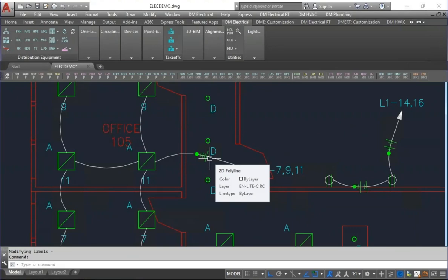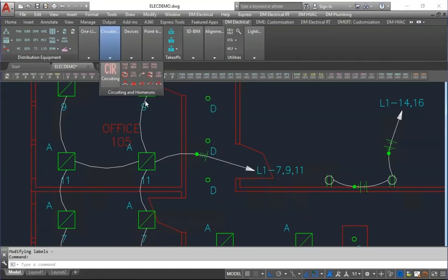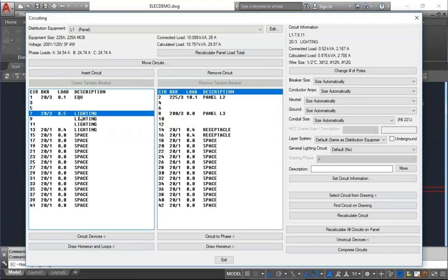That does require a 3-pole breaker. If you have 3 single-pole breakers, you can, in theory, put a breaker tie in there. So that would be a case where you'd want to turn that on. Then you'd have to document that, we have a breaker tie here, and then it would give you the shared neutral. So you can do that. It requires a little bit of manual work. With our software, you could combine them to a single 3-pole breaker.